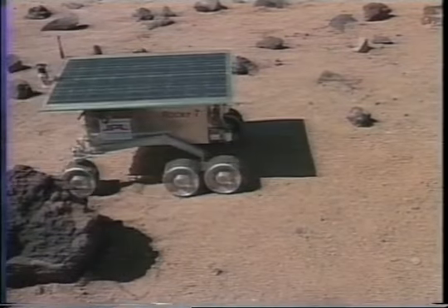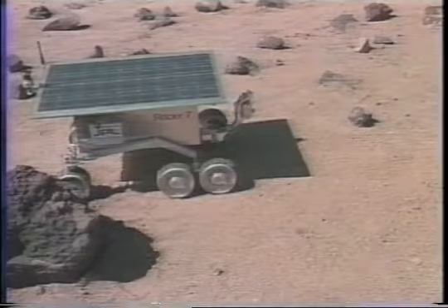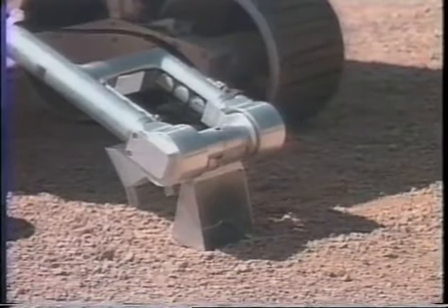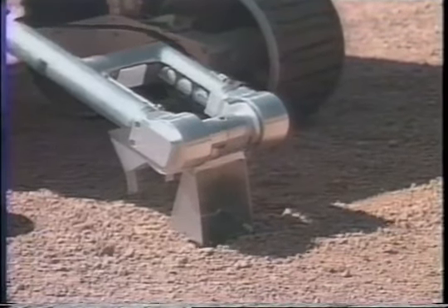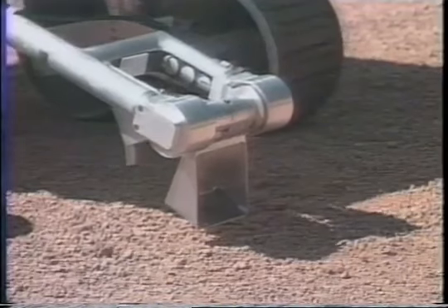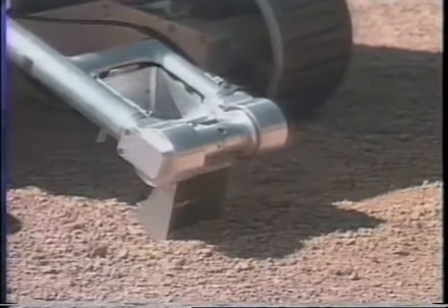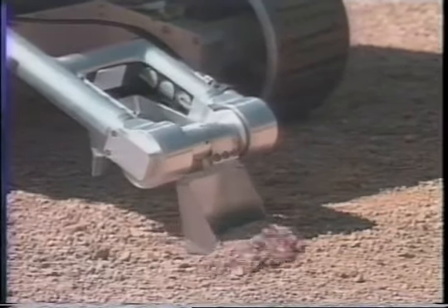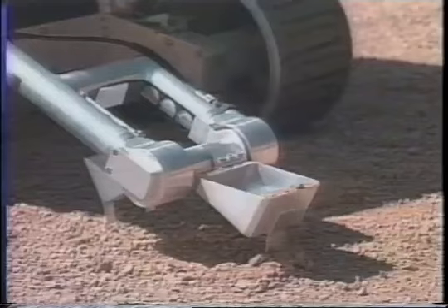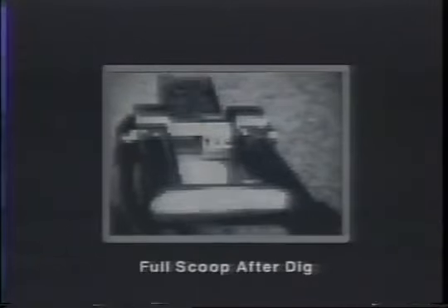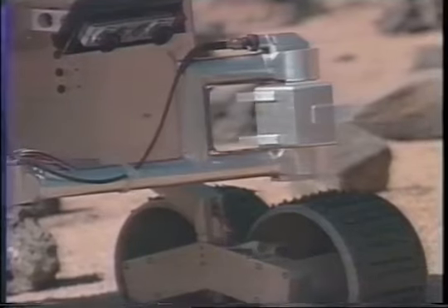At the dig and dump operation target, the rover analyzes close-up images of the target area to ensure that it has appropriate soil. If it detected rocks or pebbles, then it would automatically search the local area for a more suitable dig location. It also checks for and avoids possible collisions with rocks. After the rover completes the dig operation, it performs a visual check of the sample. If it does not detect a large enough sample, or if the scoops do not close all the way, then it reports a failure and continues.